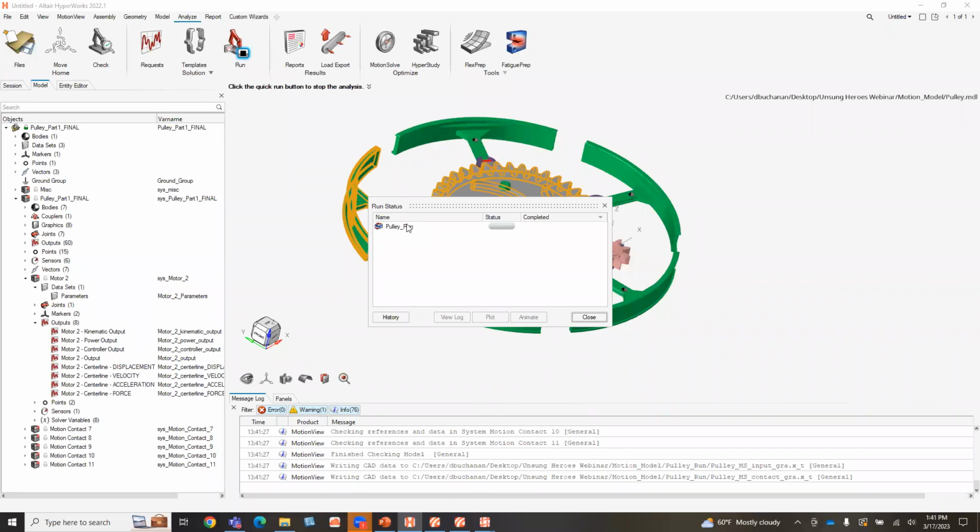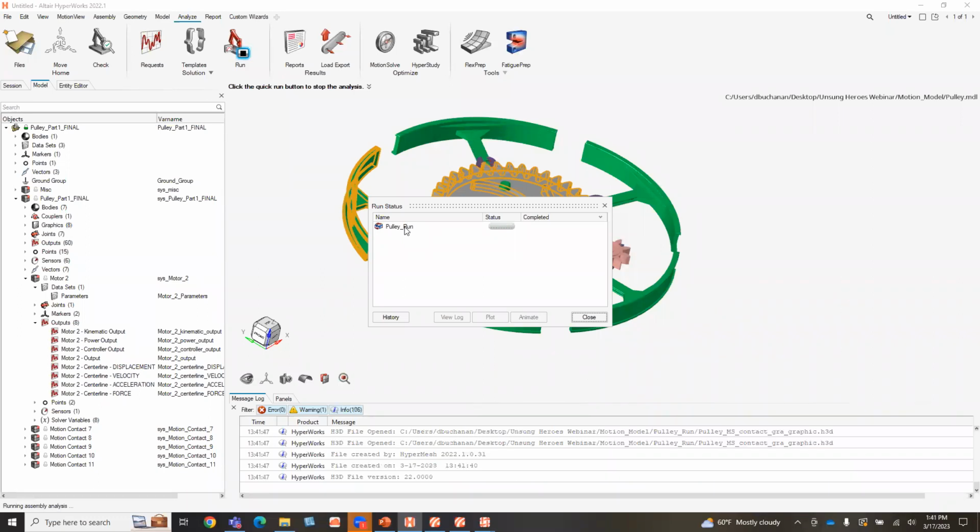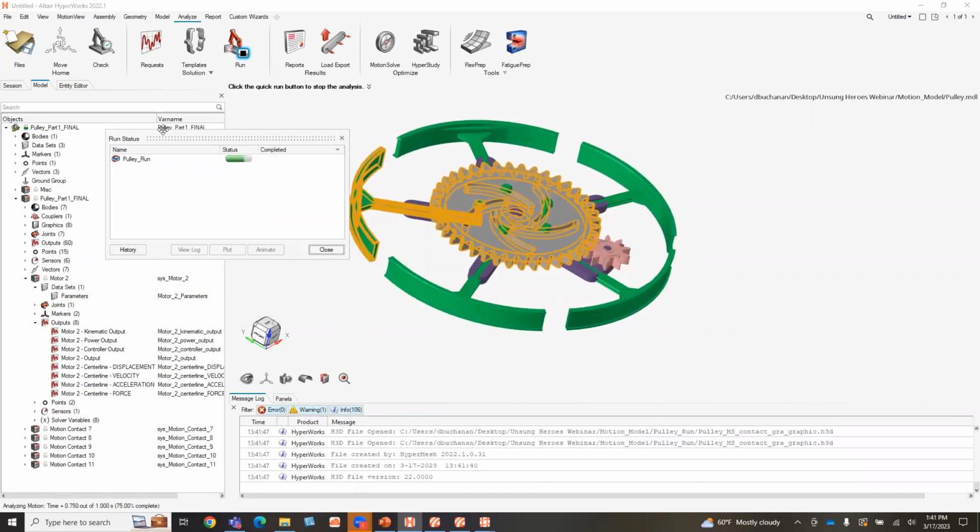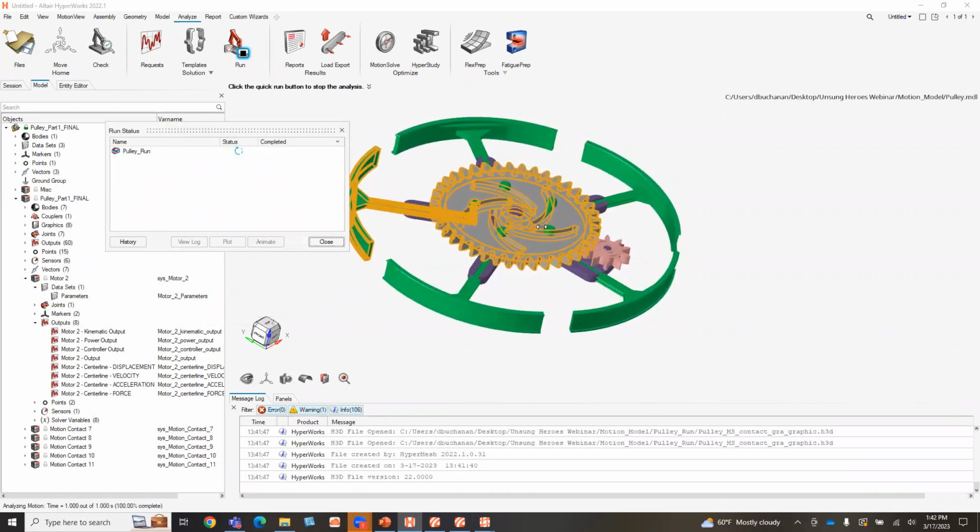One of the other things to keep in mind when we're looking at these types of results: you can see right there, it showed the animation and finished out. Like I said, a couple of minutes. If you were trying to do this in FEA, you could try and solve this in implicit FEA. That would be super difficult with all the contacts. Maybe explicit might be able to handle it, but again, it's going to take way longer because there are more equations to solve. So I think that's really where the power of using a kinematic-based solver is.